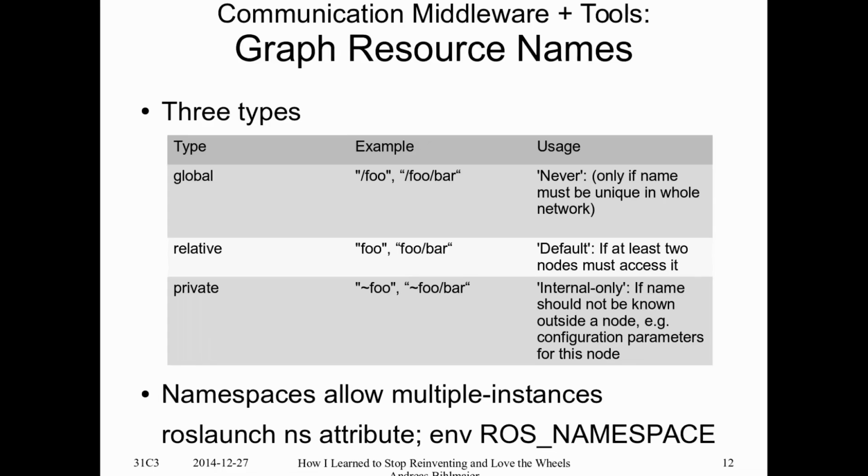push it down. So for example, if you have two webcams, you simply start your driver node twice in separate namespaces, for example, camera left and camera right, and the software does not need to know that it currently is being used together with another camera. That is just a runtime decision when you start your nodes.